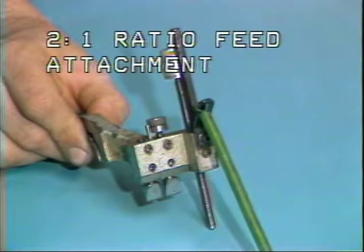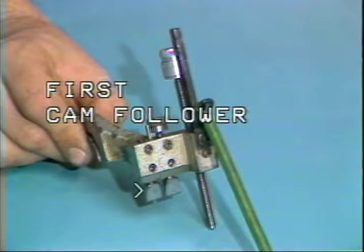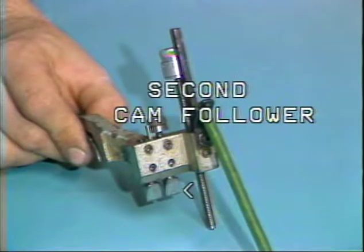This is a 2-to-1 ratio feed attachment. The maximum feed length using the 2-to-1 ratio feed attachment is approximately 1 inch. Located here is the first cam follower. This cam follower will trace the first feed cam. Located here is the second cam follower. This cam follower will trace the second feed cam or the return cam depending upon the job.